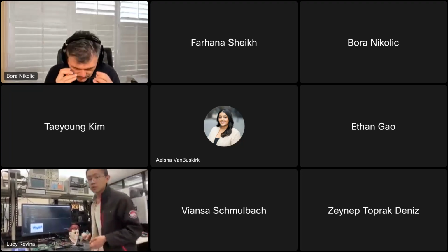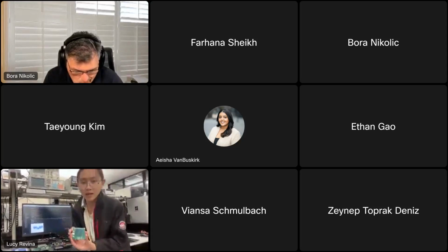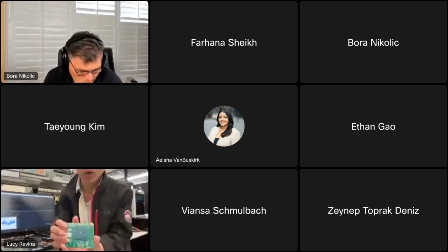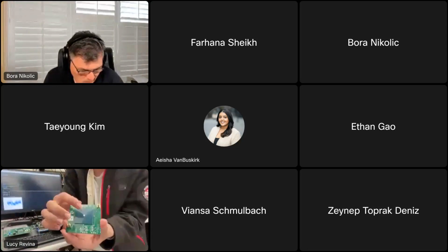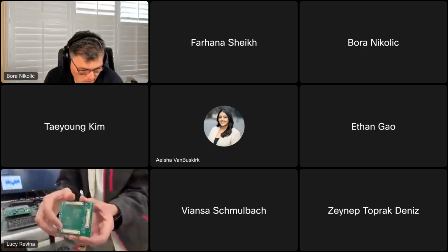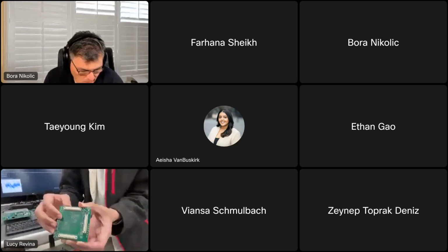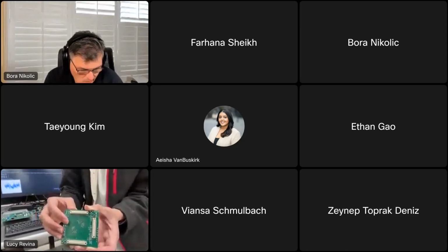So for the digital chips, we decided to do a three board system. The first board that we designed was a little SAW module over here, which takes the chip with all 4 of our quadrants and breaks out all the pins to these small board-to-board connectors and provides clocking to each quadrant of the chip to simplify design of the other boards.